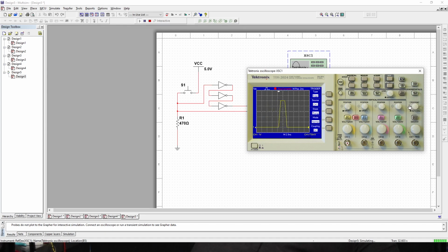We can move that signal somewhere in the middle, or I'm just going to align this bottom where the pulse begins to happen with somewhere that I could make a reference to. So I'm going to bring it right up to here. All right, there we go. All right. What else can we do? We see a pulse, and we see that this is 2.5 nanoseconds per division.